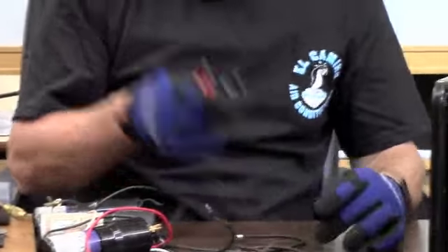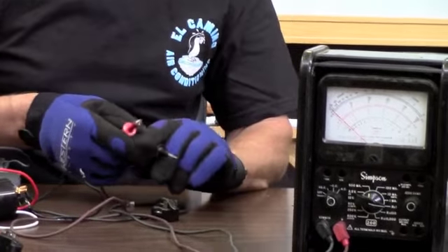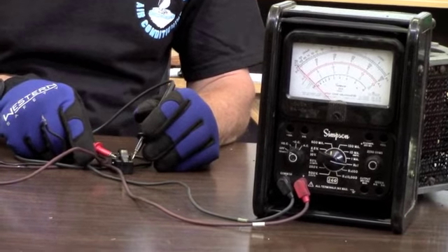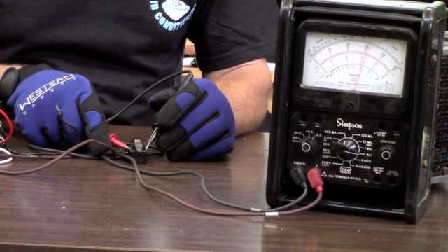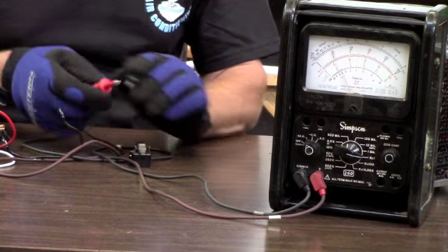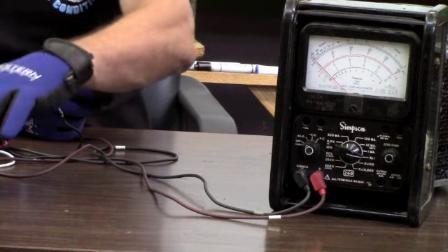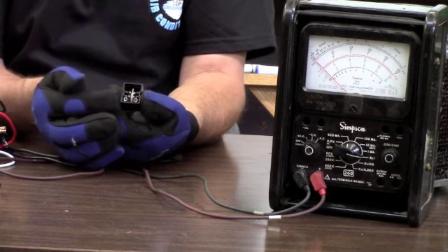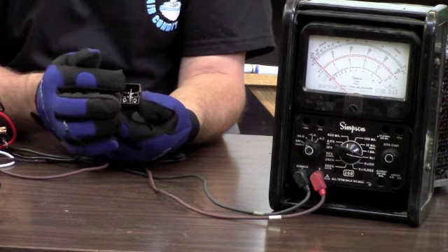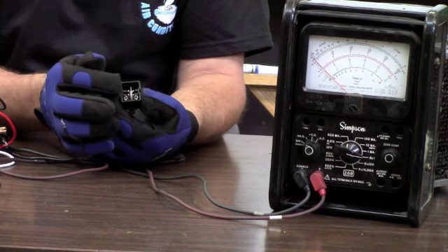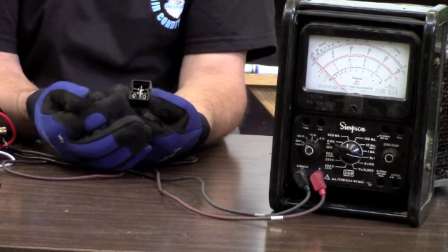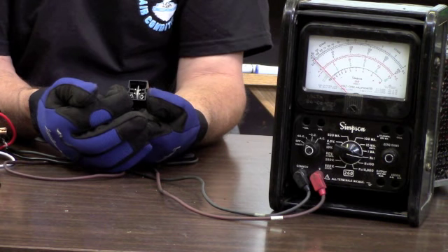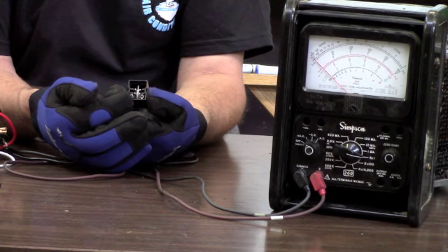So if I look at my diagram, or my meter, we're going to see I'm on the ×1 scale. So I should read about 5 or 6 ohms on the scale. Very low resistance. If I open up a PTC, I will see those leads, and then we'll see the PTC in the middle. As that PTC warms up, the resistance between these two points is going to go up high enough so that it's going to basically de-energize the start winding.